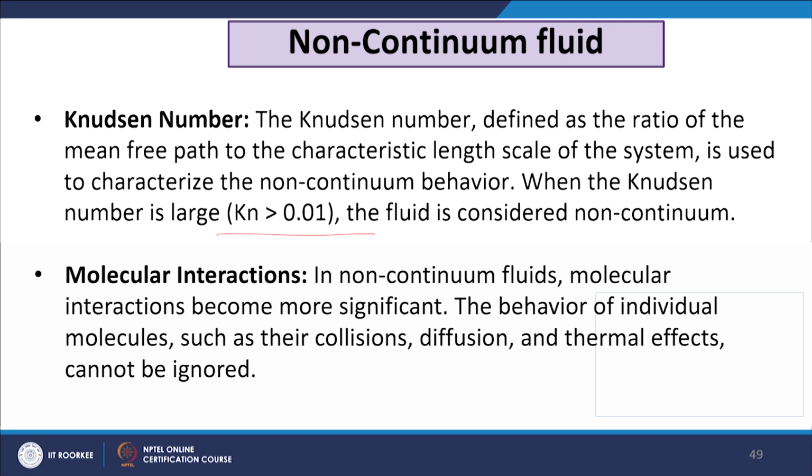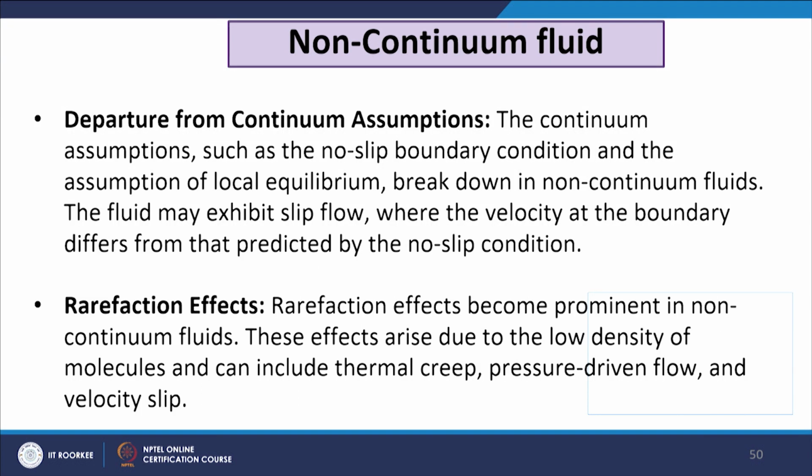Molecular interaction. In non-continuum fluids, molecular interaction becomes more and more significant, and the behavior of individual molecules, such as their collision, diffusion and thermal effects, cannot be ignored. Departure from continuum assumptions. The continuum assumptions, such as the no-slip boundary condition and the assumption of local equilibrium, break down in non-continuum fluids. The fluid may exhibit slip flow, where the velocity at the boundary differs from that predicted by the no-slip condition.